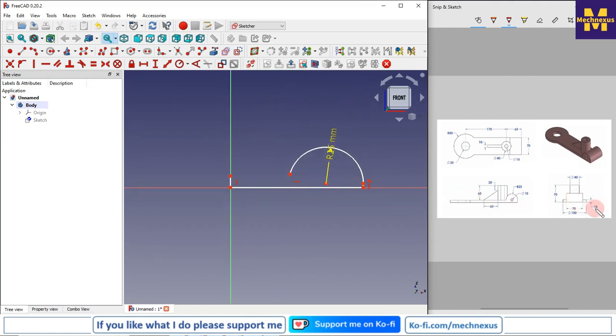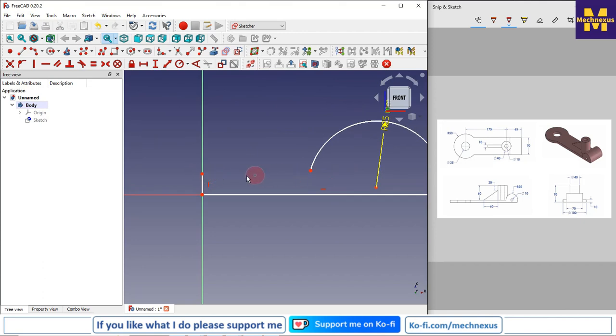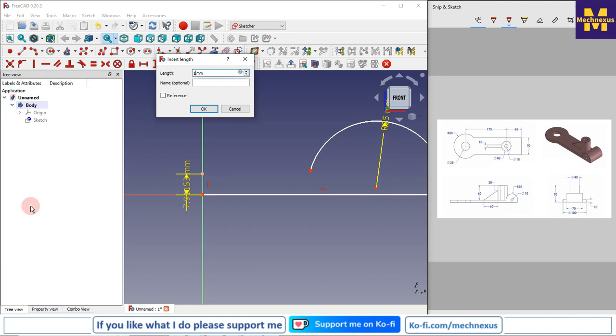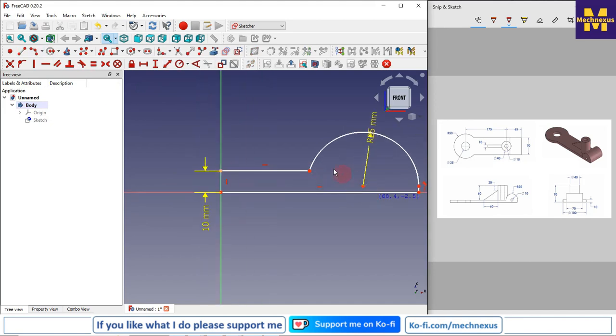Now we can see that this base plate thickness is 10 mm. So I will give the first dimension, 10 mm. I will move it outside, and now I will join it with my arc, and I will make this point and this point horizontal.